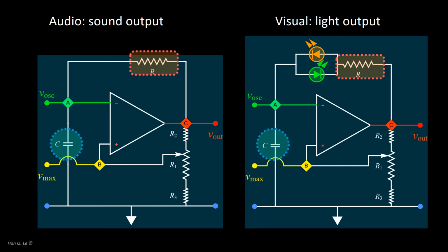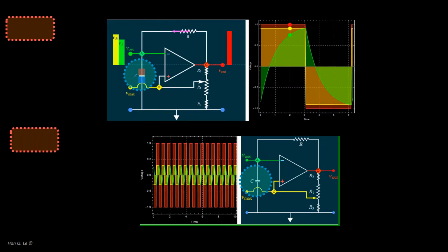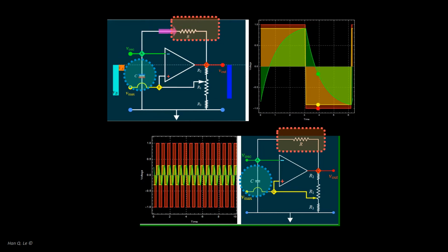This creates a non-stationary condition, that is, the circuit cannot settle to any stationary state with constant voltages and currents. Instead, it keeps on vacillating between the states. Vacillation, or oscillation, entails the concept of frequency. The top graph shows how the OpAmp cannot stay still, because the output feedback tries to stabilize, or make the two inputs roughly equal, to no avail, because the moment the inverting input, VA, catches up with the non-inverting input VB, it takes only a small overshoot or random noise to make the output flip the non-inverting input VB the other way, and the inverting input VA starts the chase again in the opposite direction.